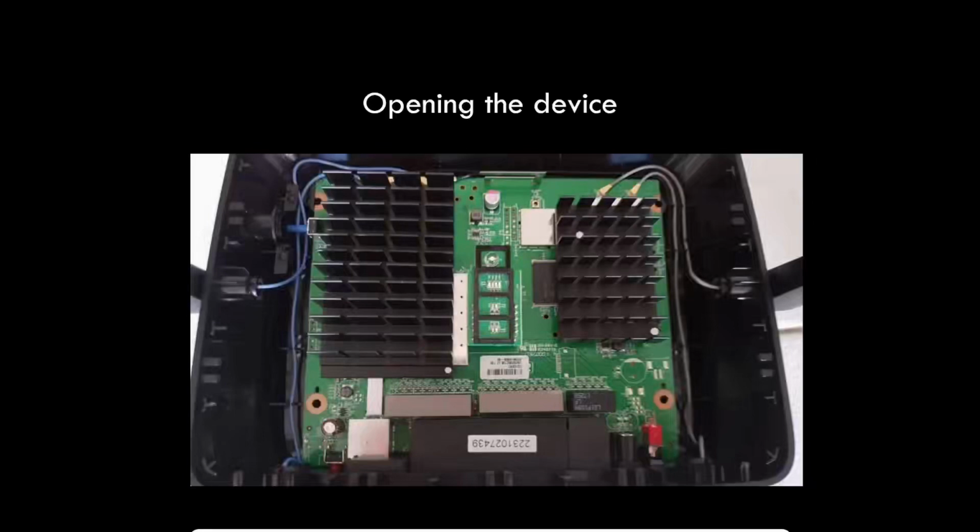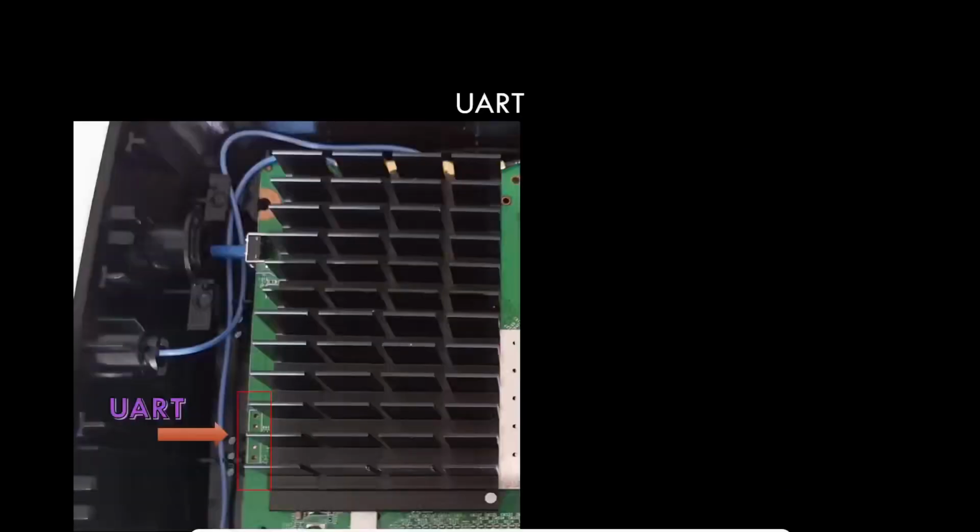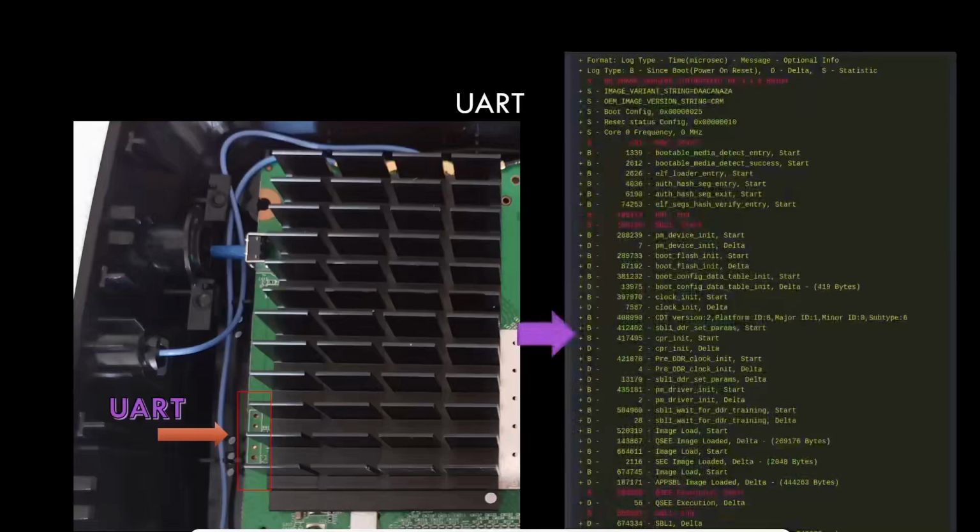Well, opening the device is the first thing that any hardware attacker would do. Really simple and easy, nothing really special. What you see here is the PCB. And you see already a few pins that may be interesting. And in our case, the first thing that you would always like to find is the UART. I mean, this is really basic stuff. It was really easy to check, just an oscilloscope, or just plug some pin and see what happens.